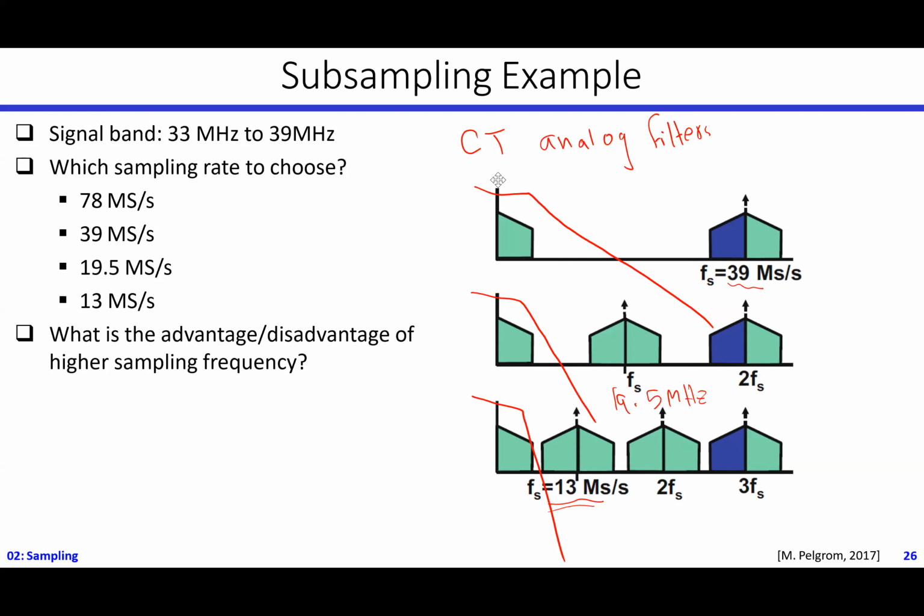So if I make my life easier by choosing a low order filter in the analog domain, then in the digital domain I can do decimation. We will describe it now. Then I can gain the advantage from the digital circuits and reduce the complexity in the analog domain.